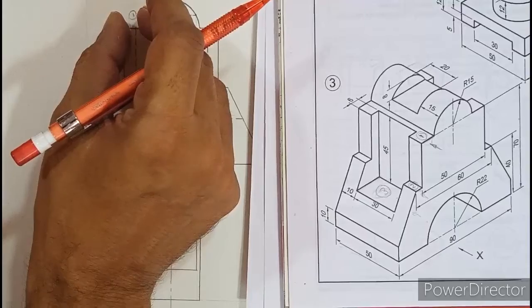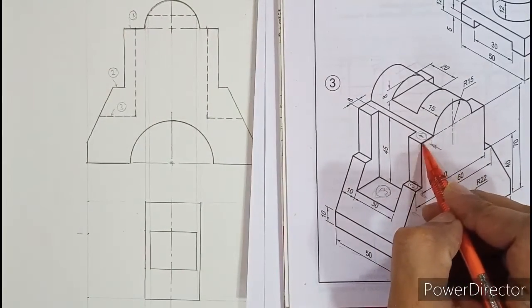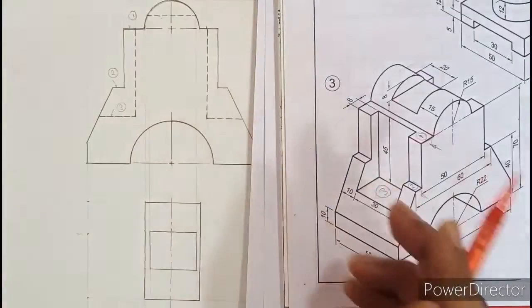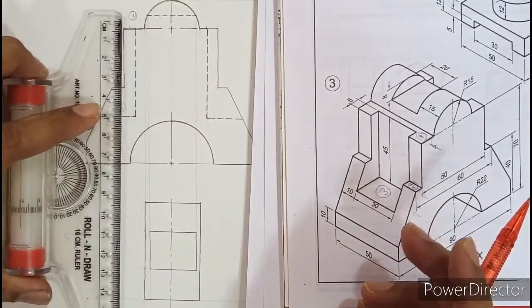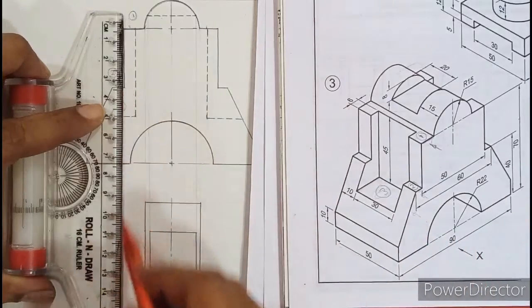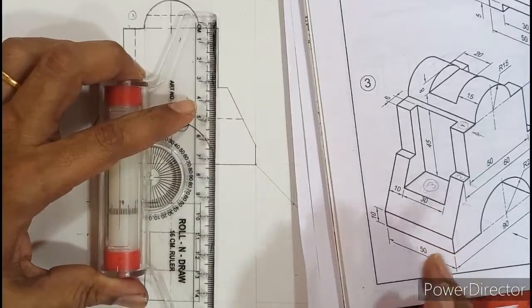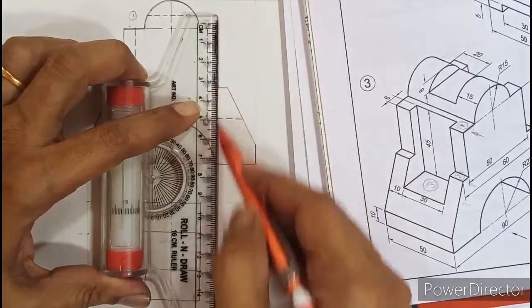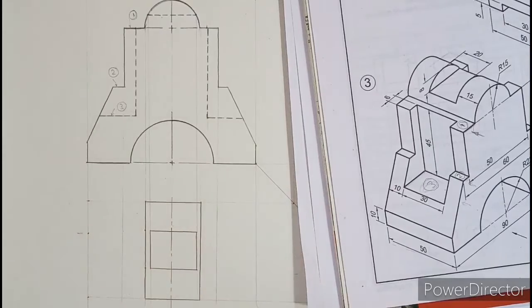First only think about 1. For surface number 1, you need to project this edge from the front, and that is the shoulder. So I will align from here, roll back and draw a light line. Because the object is symmetrical, we will do this on both sides. So even here we will do that. I projected from both sides as you can see.